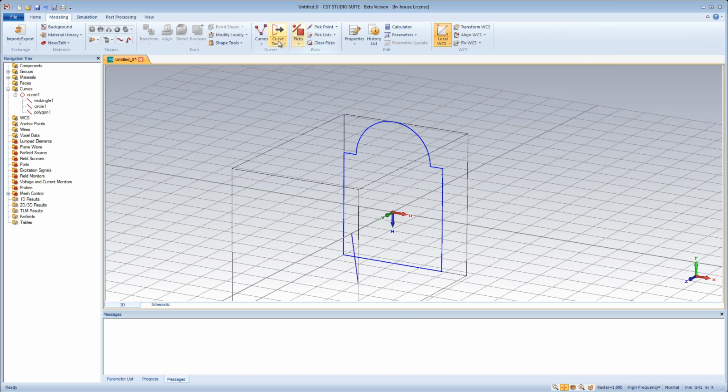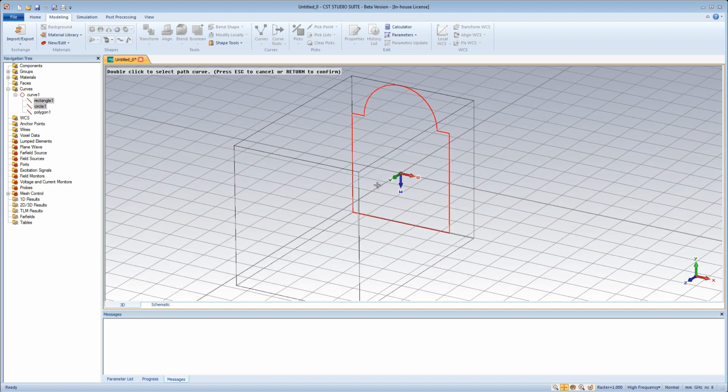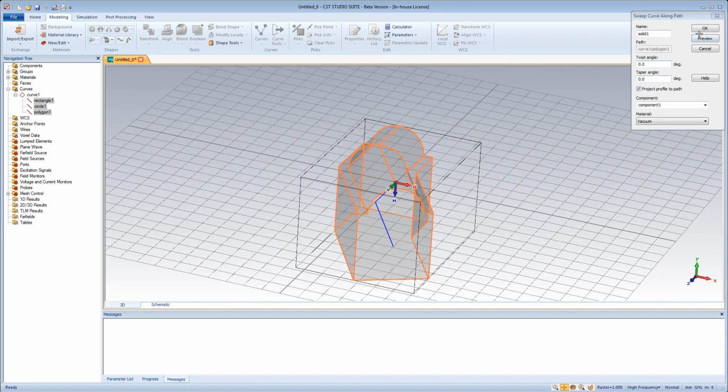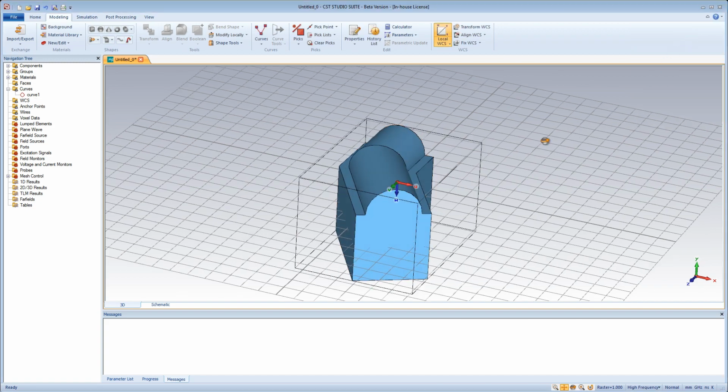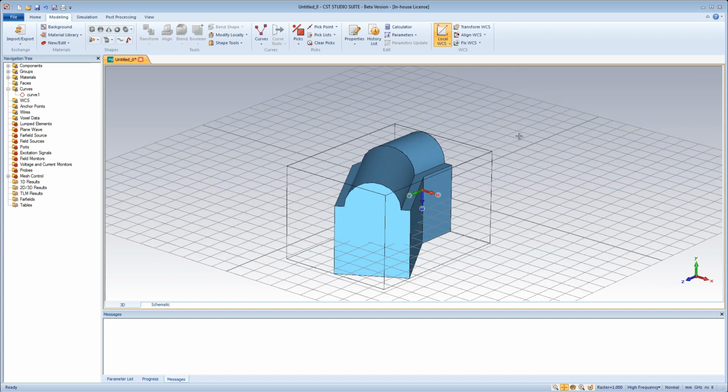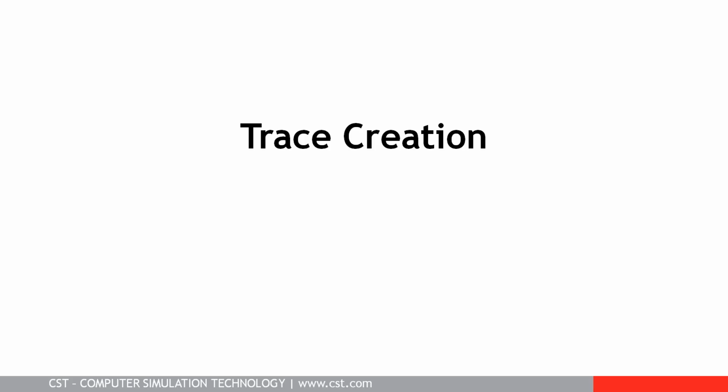This can be initiated by choosing Curve Tools, Sweep Curve. As soon as this operation is activated, you will be prompted to select the profile curve. Double-click on the curve consisting of the rectangle and the circle. After the profile is selected, you will be requested to double-click on the path curve given by the polygons curve here. This short introduction into curve modeling provides a very basic understanding of these powerful structured drawing tools.